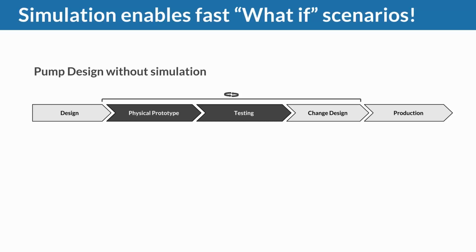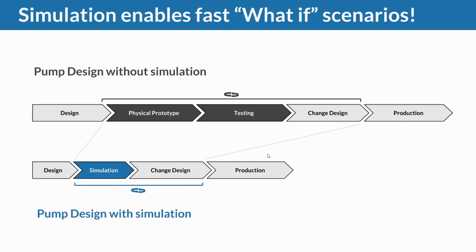So a traditional design process of a pump without using simulation always requires you in the beginning to spend significant time on your initial design, making sure it actually works or you're confident in it, build a prototype, put it on a testing stand, and then measure the performance curves of the pump, and whether or not this is sufficient for the requirements you have for this pump.